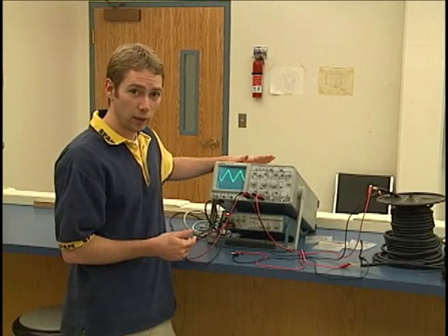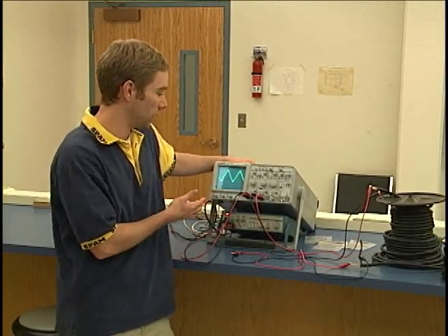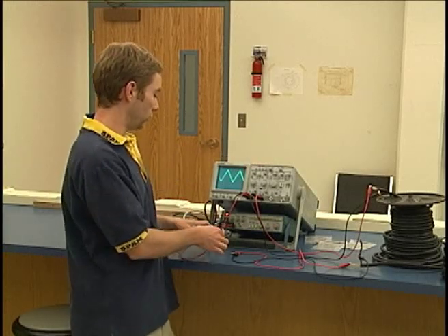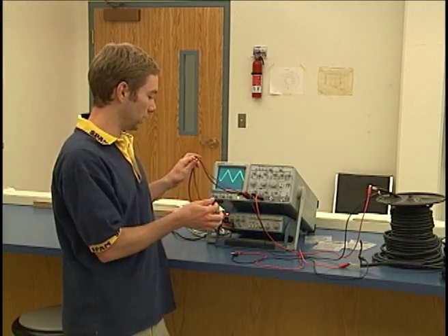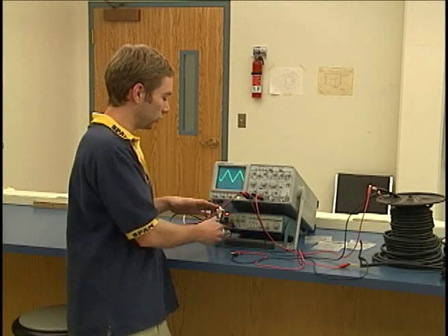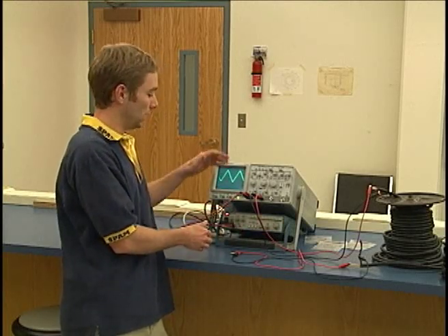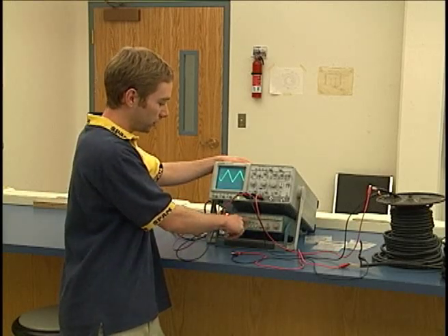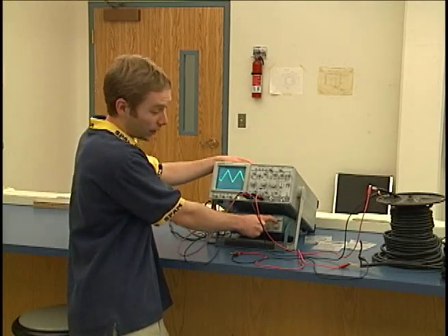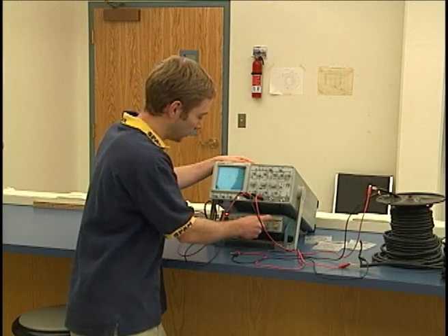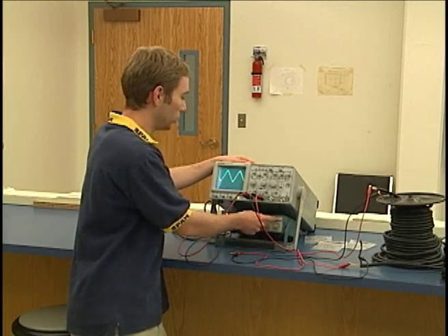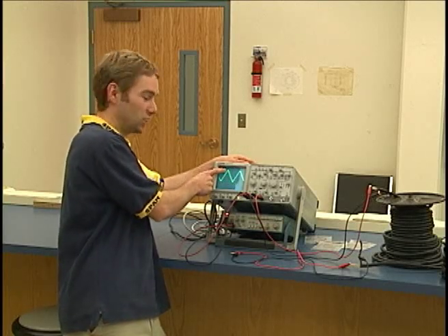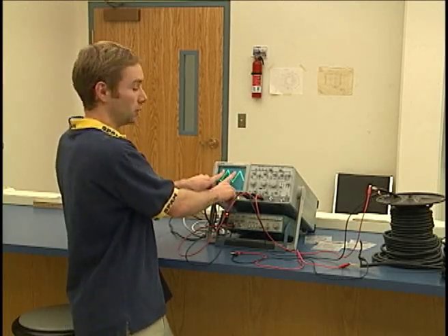So for this part of the lab, we'll just be using the normal analog oscilloscopes. First what you need to do is set up just an initial signal from your AC power source down here, hook it up to channel 1, and get a 1 megahertz signal. And you're going to want a triangle wave for this one, as opposed to the sine wave or the square wave or anything like that. Put it on a triangle wave. This will give you nice little pointy peaks, so you can do your measurements a lot easier when you're finding the offset between the peaks.